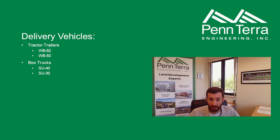So the most common ones we use, I broke down into categories. For our delivery vehicles, we're most commonly using a WB-62, but sometimes we're asked to use WB-50s for tractor trailers. And for box trucks, they are SU-40 and SU-30. That's a 40-foot long and 30-foot long box truck.